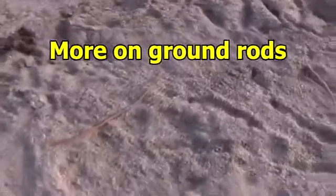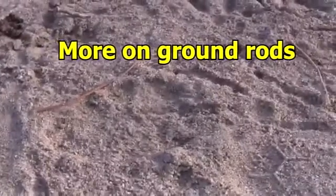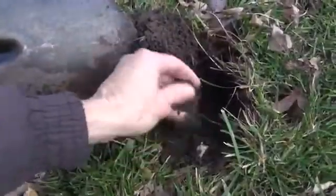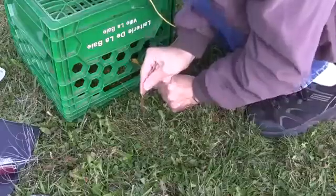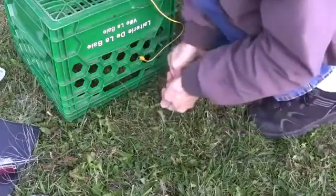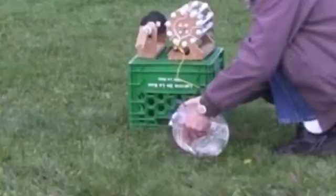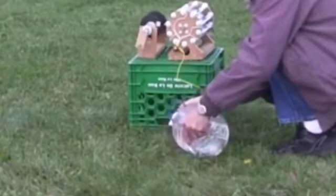For a ground rod to work well, the ground does have to be electrically conductive though, meaning it has a low resistance. Dry sand like this is not very conductive, and is a bad ground. But moist soil is fairly conductive, and is a better ground. Also, the more ground you connect to, the better. Here I just pushed some wires into the ground, and it wasn't very good. I even poured water in to help, but it still wasn't great.